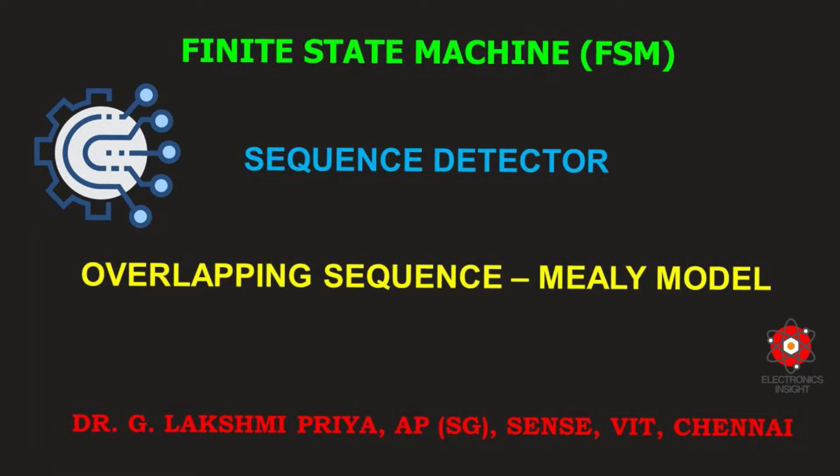Welcome you all for an interesting video on digital logic design, where in this video we are going to concentrate on designing a finite state machine, especially for the overlapping sequence detection using Mealy state machine. As we already know, synchronous sequential circuits will change the states for every positive or negative transition of the clock signal based on the input and what type of edge triggered flip-flop that we're going to use for